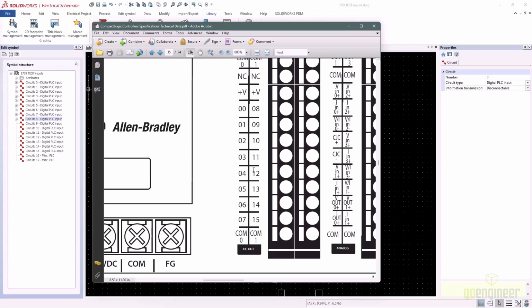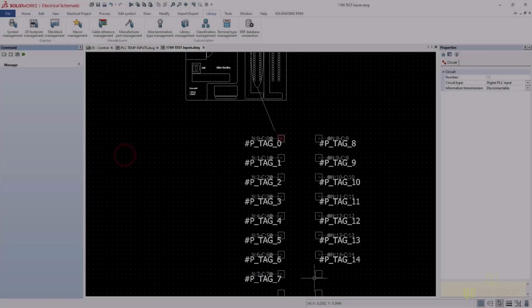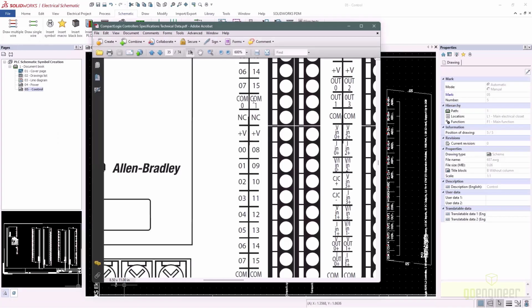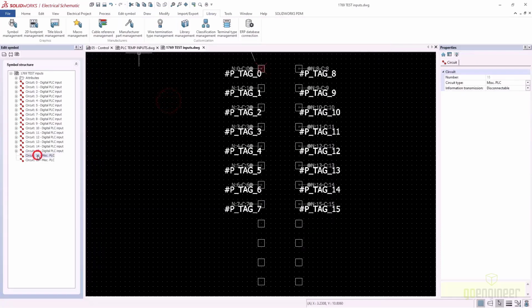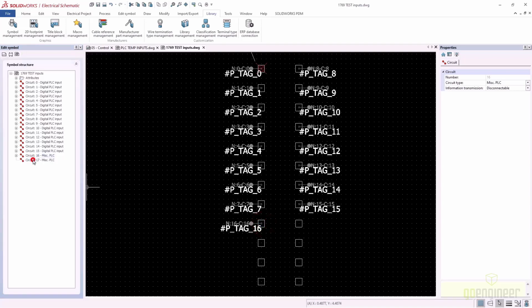and now the next set of comms is for the digital output. So we're not going to worry about that, but I did notice that there is no connection after these 2 comms. Notice here, COM 0, COM 1, and then no connection, no connection. All right, before I start the next card, let's go ahead and drop in these 2. So the COM 0 is supposed to be on this side, on the left. And then the next one here is on the right.